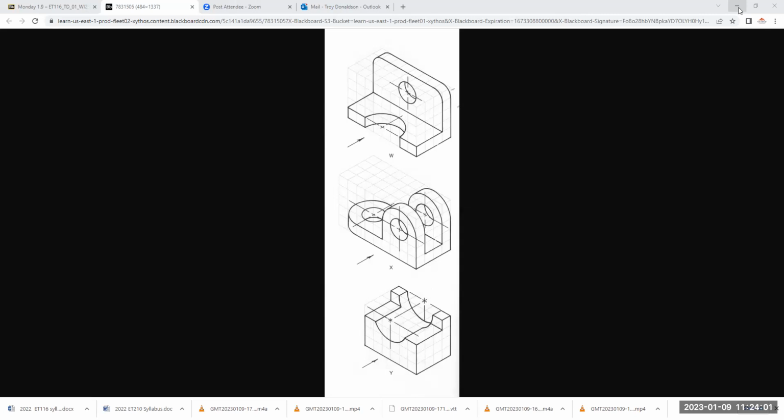So I do a lot of construction lines, like just less math, more construction lines. I can get rid of that now, and then I can trim. And I'm a typer, so I haven't gone up to the ribbon once. Sorry, that's probably generational, right? You're probably ribbon drivers and you'll go up there all the time, but I hardly ever do. So you can see I typed in TR for trim. I'm doing that a little bit unconsciously. I know it's up here somewhere. It's right there. And lines there and circles there.